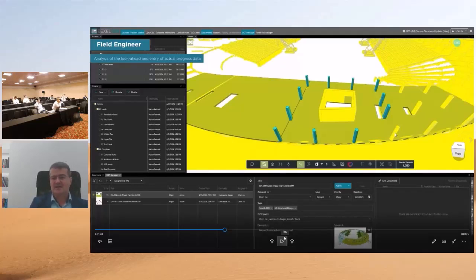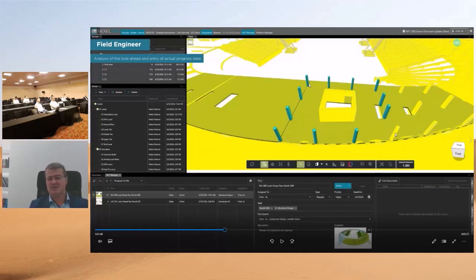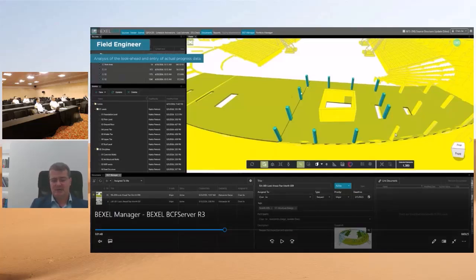In this case, it is based on the elements, but for some activities, we also have on this project a workflow where you have a different selection of elements for just the concrete pouring activity, and different formwork. So you can define how you will do this.